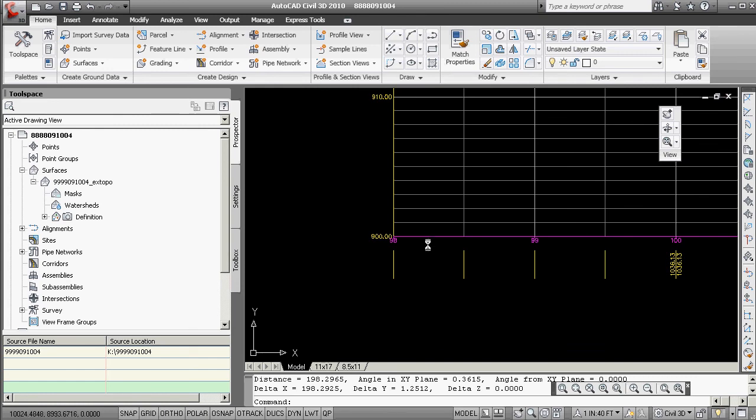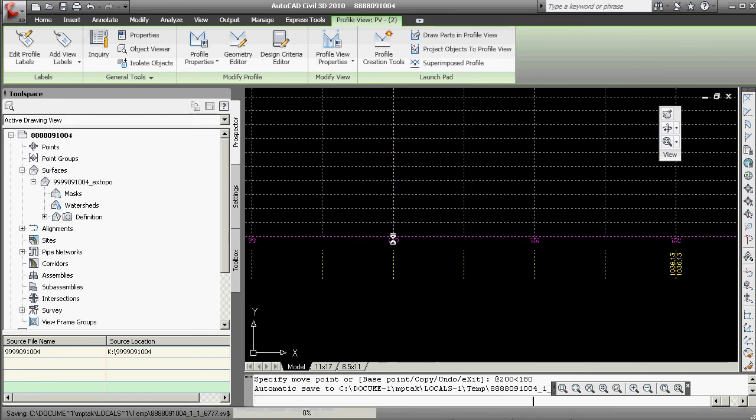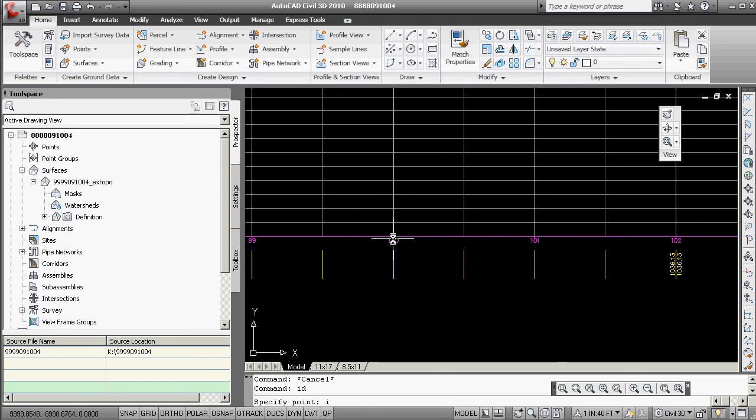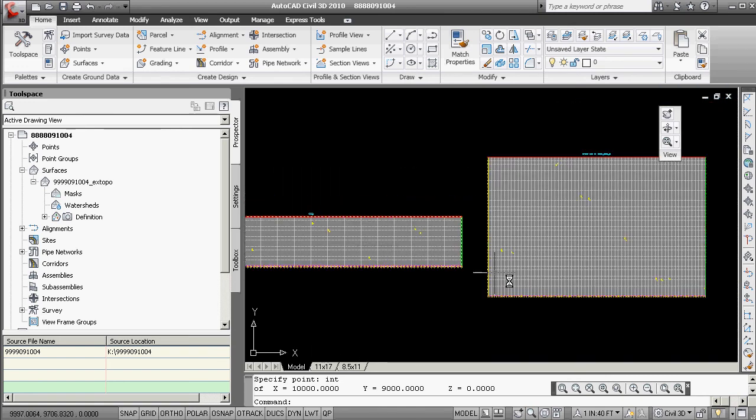We're going to grab this, left click, spacebar, at 200, angle 180, and we're going to check and ID the intersection of that one, station 1000, elevation. Alright, so now you've got essentially what you need to start doing the rest of this, which we'll pick up in the next video. So key, keeping profiles in the right spot. We'll pick it up in a minute.